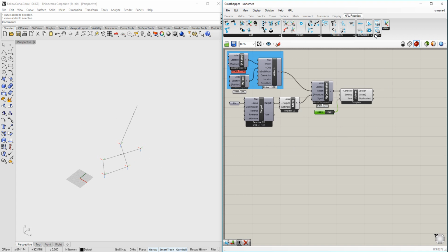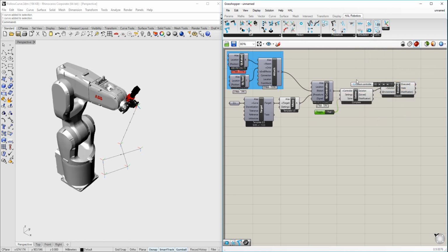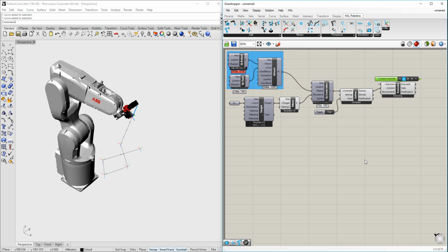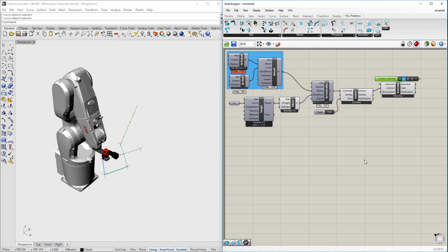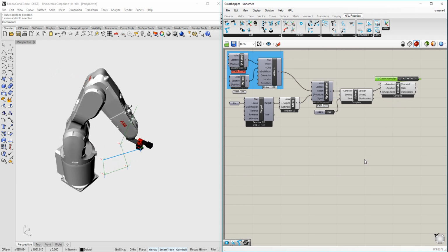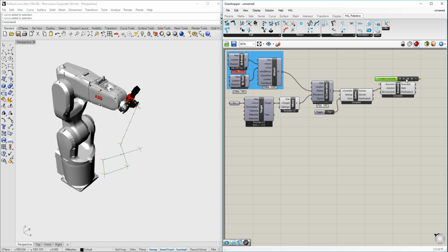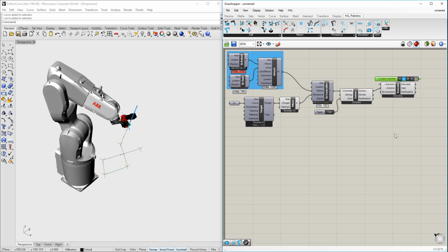Once we've solved, we can simulate. So again, on the Simulation tab, Execute will place in an execution component and this execution bar. If I plug solution in here, we can see our robot comes up again, and if I hit play, then the robot is going to follow that trajectory. By default, it'll stop at the end. We can reset, hit play again, and ask it to loop.